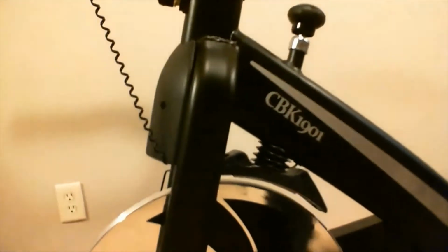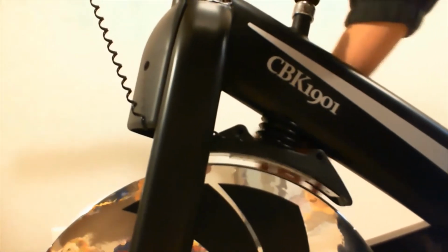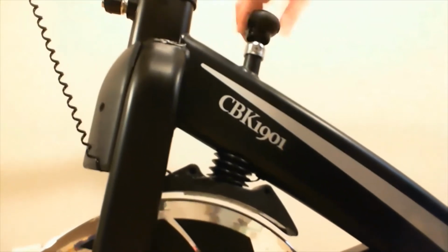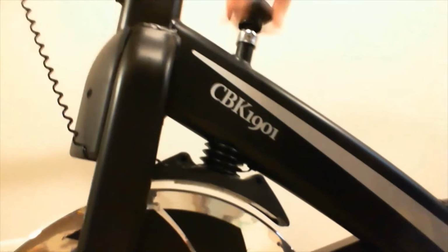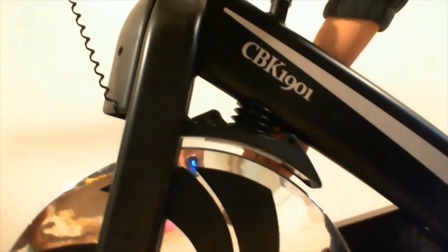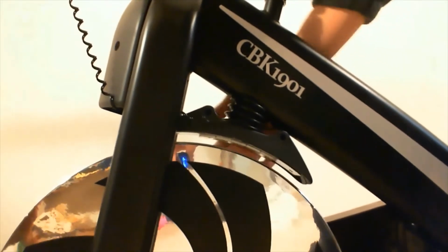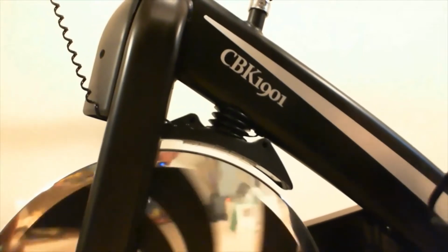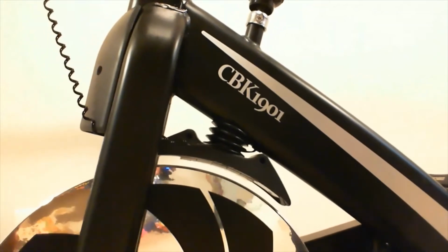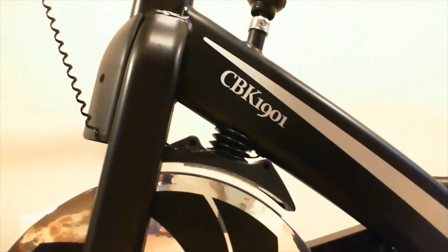There is no brake pad on this spin bike. Instead, there is a metal wheel and a magnetic field. Up here, there is a bunch of magnets, and as I twist this knob, it moves the magnets closer to or farther away from the metal wheel. We have a piece of metal, which is conductive, and a magnetic field, and as I rotate this, we have relative motion between the magnetic field and the conductor. So we know that we have an induced voltage because we meet the requirements for generator action.